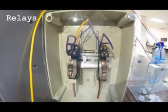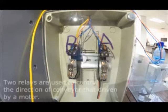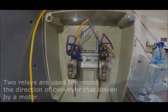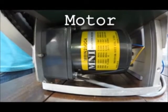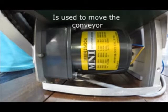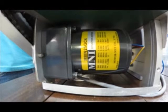Next component is the relays. We have two relays, the right and the left relay. Basically, the right relay is used to control the operation of the motor, and the left relay is used to control the direction of the conveyor. Here is the motor, which is used to move the conveyor, and is controlled by the right relay for the on and the stop of the conveyor.